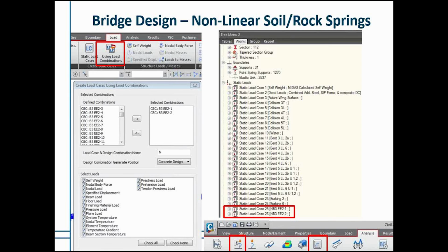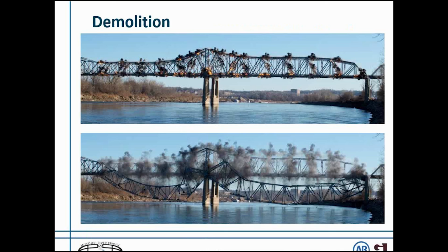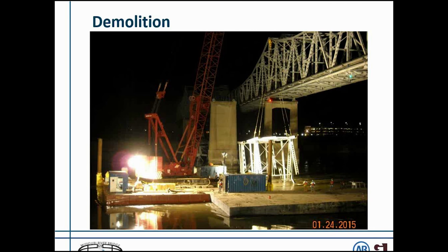As far as constructing this bridge, we first had to demolish the Fairfax Bridge to make room for our new bridge. In this process, when the demolition occurred, they had to remove each piece of the existing steel braces from the navigational channel within 24 hours of the explosion. So they used a barge and moved each piece to land and disassembled it there.